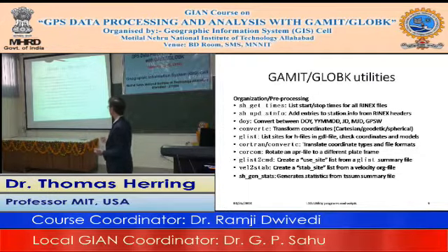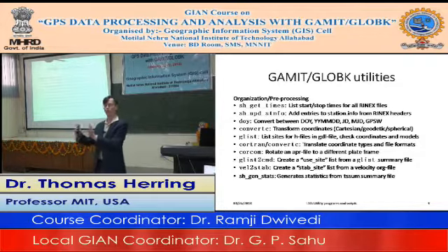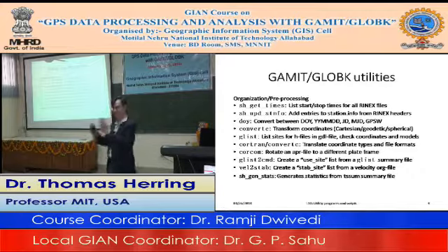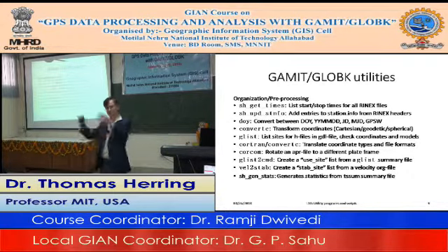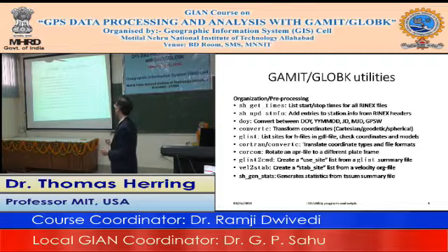There is a shell script called SHGet times. When you have Rinex files that someone has sent you, some data files that you've got to dump, and you don't quite know what's in them, this tells you the start and stop times of all the Rinex. If you've been doing campaign survey measurements, for example, and you have these 3 or 4 hour sessions, you might ask whether you process it as a big part of one day, or process it specifically for that time. SHGet times allows you to look at when things start and stop to give you an idea of what actual interval you want to do.